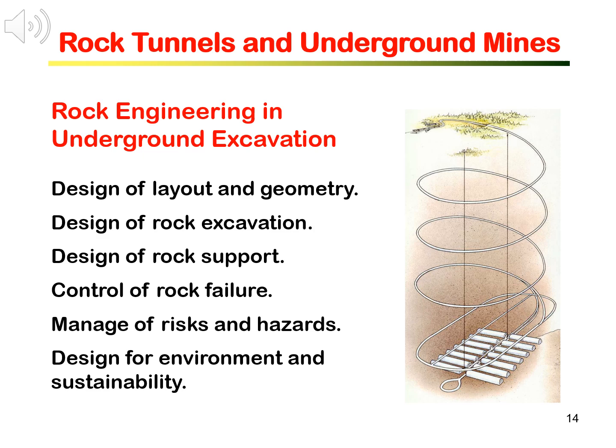As illustrated by the design of a liquefied petroleum gas storage cavern complex on the right, we will need to design the underground layout and the geometry in terms of depth, separation, and size, to select rock excavation methods and machines, to adopt rock reinforcement and support, to manage risks associated with and hazards induced by underground excavations, and to consider the environmental effects and sustainability.